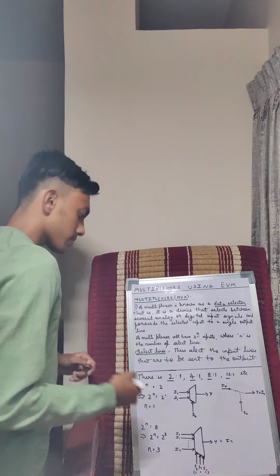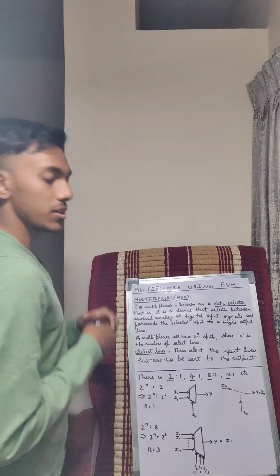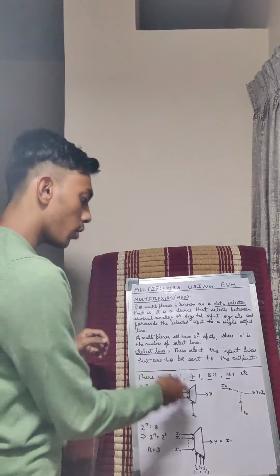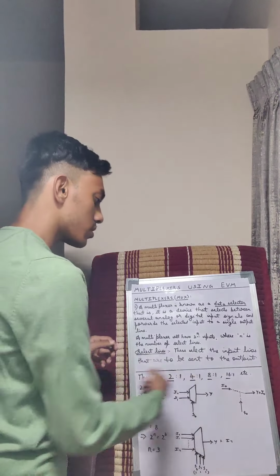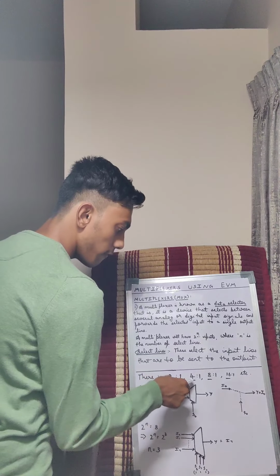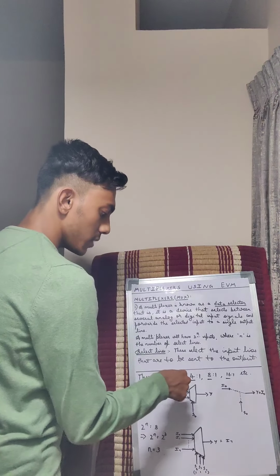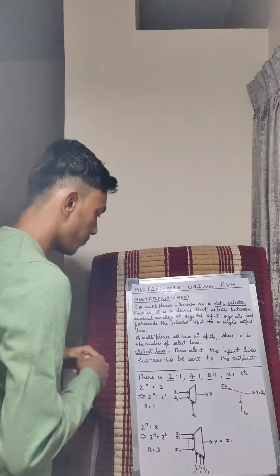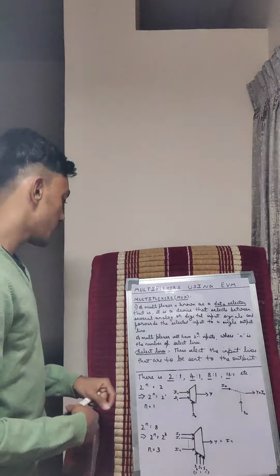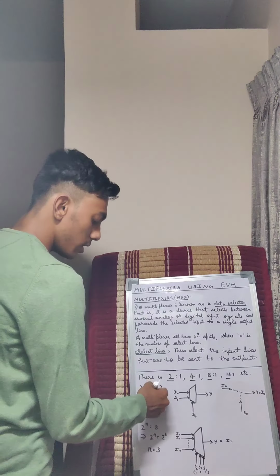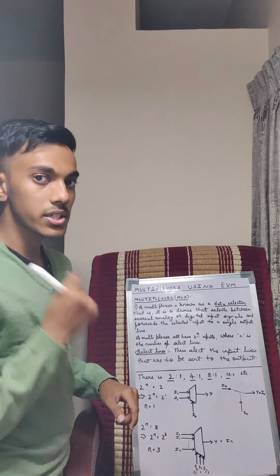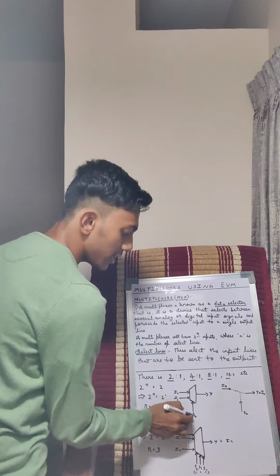Okay. Now moving on to the different types of multiplexers based on the number of inputs. We have 2:1, 4:1, 8:1 and 16:1 multiplexers and so on. Now let us consider the first numbers in these ratios, 2, 4, 8 and 16. Let me equate this 2 to 2 power n from the previous discussion. What do we understand? We get to know that the value of n is 1. That means that I'll have to make use of a single select line. Let me call that S0 here.